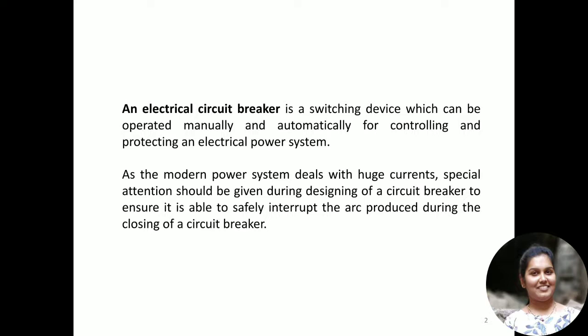And the major difference between a fuse and the circuit breaker is that a fuse does a single action. That is, when it detects an overcurrent, it burns itself in order to protect the load. Whereas circuit breakers will do this action, and in addition to this, it again comes into its normal condition after the overloading or overcurrent condition has settled down.